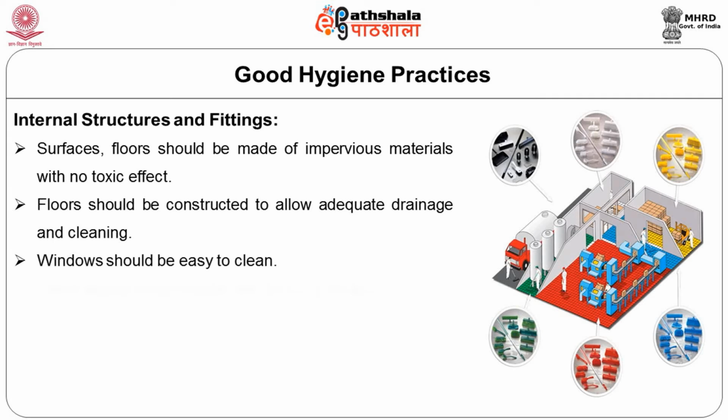Windows should be easy to clean. The design should be such that we are able to clean the windows, and they should not build up dirt, and where necessary be fitted with removable or cleanable insect-proof screens. So wherever insect screens are expected, we should be able to remove and clean them and then refix them. Where necessary, windows should be fixed. Doors should have smooth, non-absorbent surfaces that are easy to clean, and whenever necessary, we should be able to disinfect them if you think there is likely to be infection.